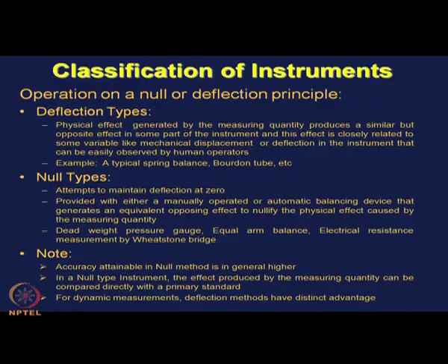It may be noted here that the accuracy attainable in null method is in general higher compared to deflection method. In a null type instrument, the effect produced by the measuring quantity can be compared directly with a primary standard.